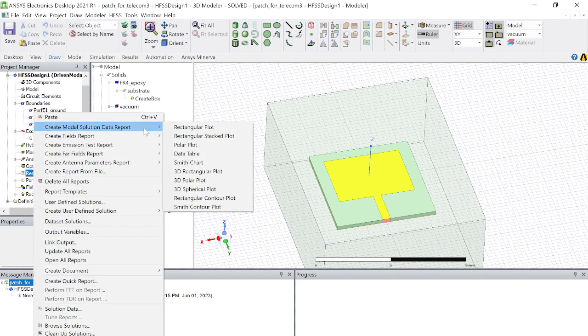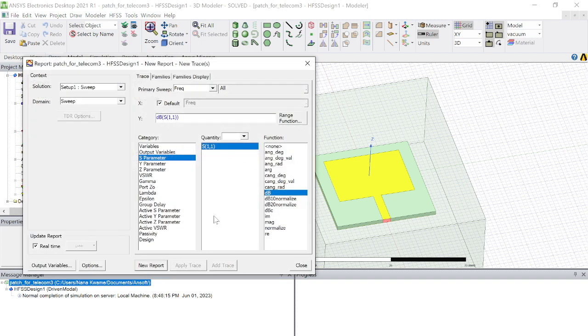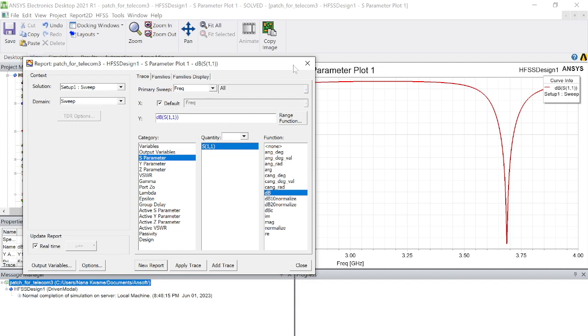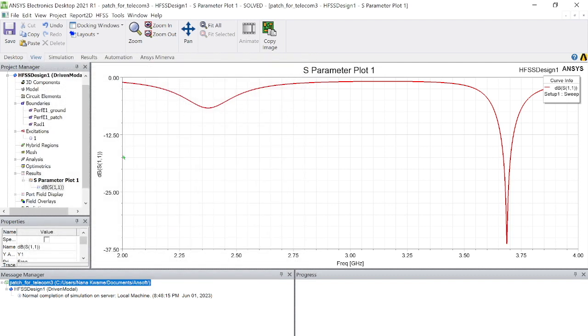So we will look at the reflection loss. Check that it is in dB. Plot. Alright, cool. So usually we have a standard that we check, that is -10, and it simply means that when the reflection loss crosses the -10, we have most of the voltage or the current that we fed to the antenna being transmitted with least error.